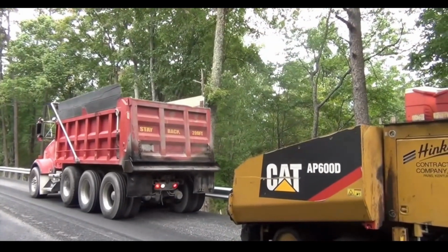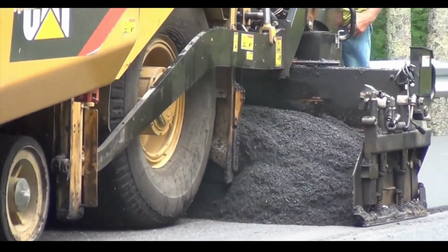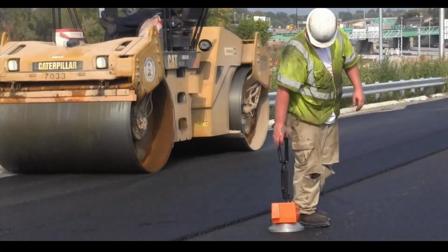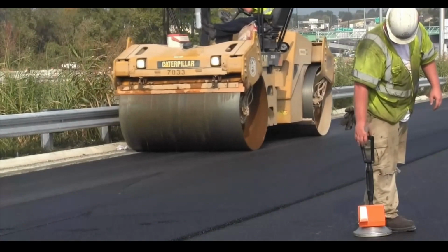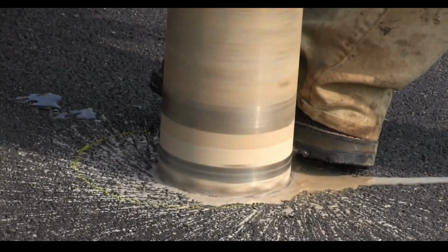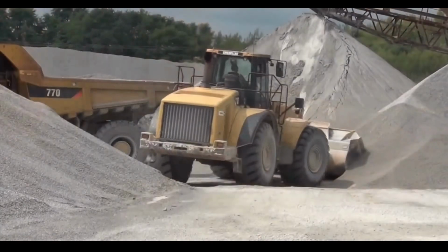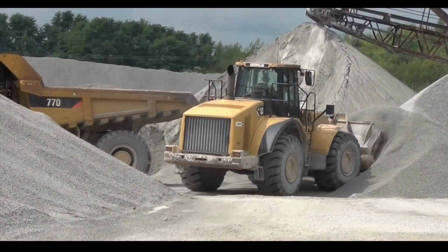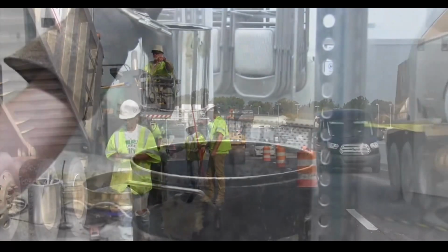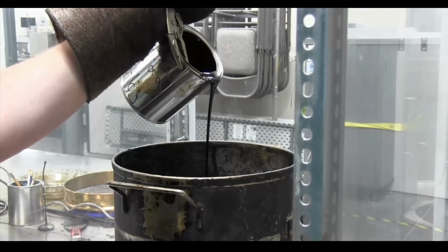Once the truck reaches the job site and is unloaded into the paver, the technician will check the temperature of the mix and perform a visual inspection. Special testing gauges are used during construction to check the density of the mat. After the asphalt is compacted and cooled, cylinders of pavement called cores can be drilled out and examined for thickness, density, and air voids. From the stockpiles to the roadway, a quality control technician is essential for a consistently successful paving operation. Their education and experience make asphalt paving a truly scientific endeavor.